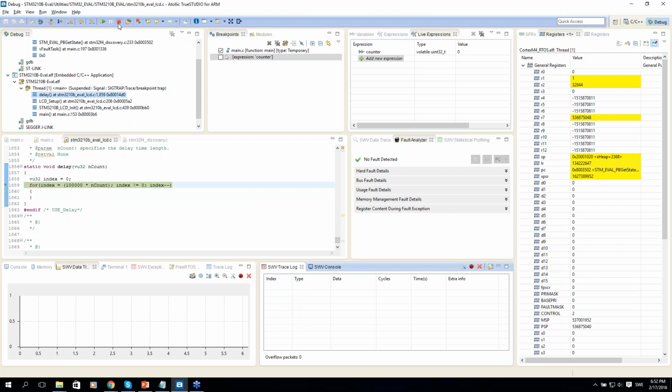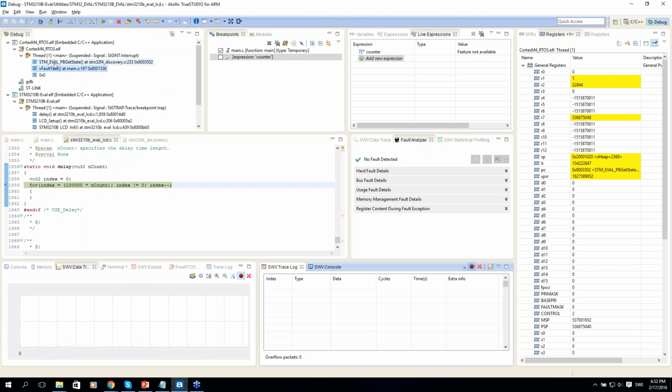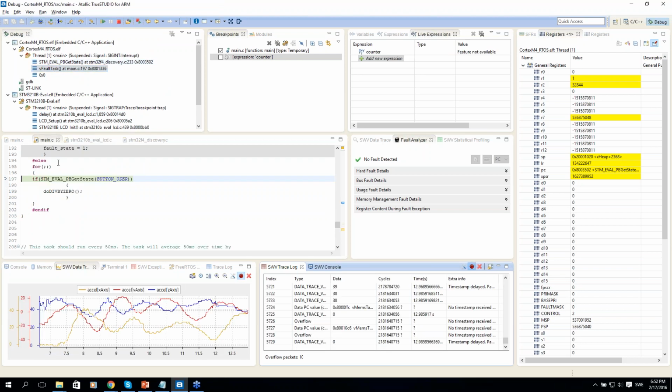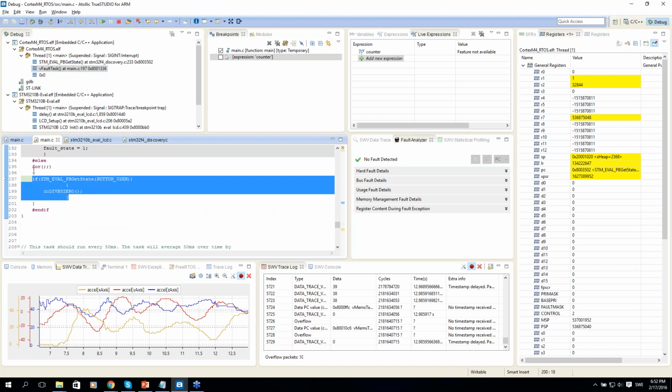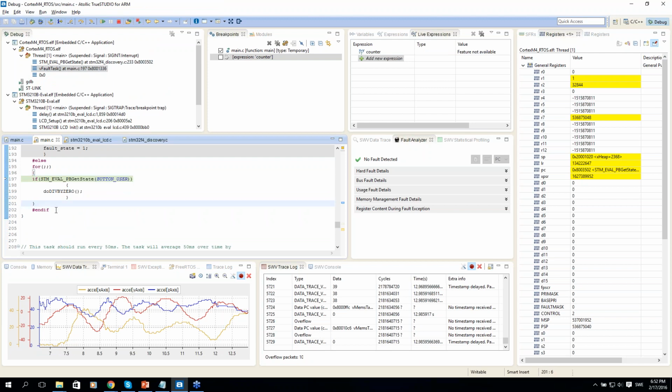So what I think the question is saying is, let's just take something. We could instrument this application to put out a byte on the ITM line here, and then another byte here. Then by timestamping this byte and this byte, we would be able to see how long it took to execute this part. What they are searching for is a way to do a simple delta of those timestamps, I believe. And no, there is currently no way to do that in a simple one-click operation, unfortunately.